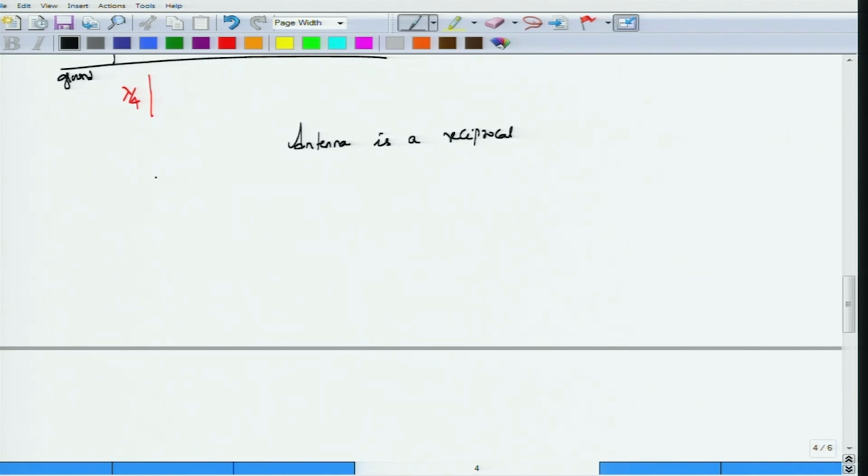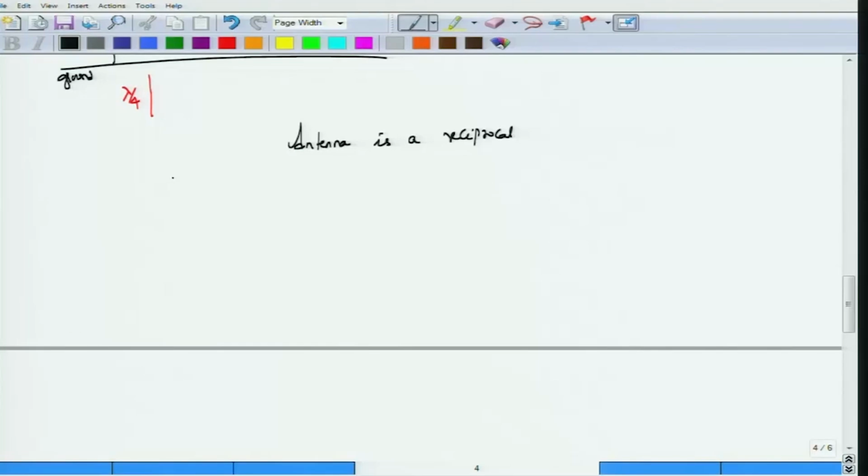Moreover, if you assume that the antennas are placed far apart, in such a way that the incoming radiation is essentially a plane wave, then the power density that the antenna sees would be multiplied by some effective area. So, it is like a catchment area of the antenna which will capture the incoming energy. Assuming that the beam patterns are matched, it will capture the energy coming in the form of a plane wave, in what is called the aperture area.